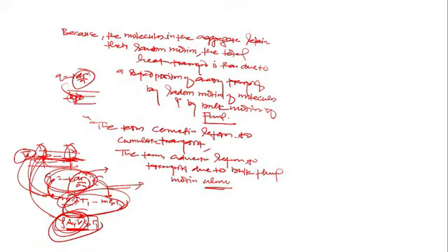m dot Cp is due to bulk flow. Clear, beta? So this energy transfer is due to bulk flow only, purely bulk flow or purely advection. This is purely random motion. The random motion plus bulk flow is combined motion, and combined motion is called convection. Now it's clear to everyone.